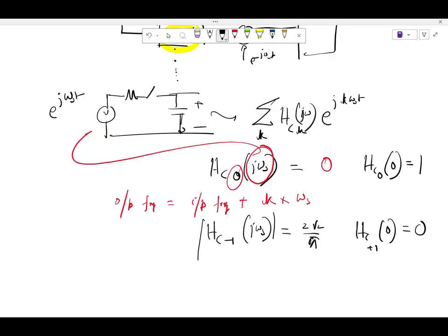One is finding out H(tau), putting that value. But today what we did, we took the assumption of a high RC time constant and related this with averaging, and we only found the transfer function from an averaging activity of the input sinusoid. So I did it only for the particular case of omega equal to omega s. Satisfy yourself by doing it when omega is away from omega s, maybe omega equal to multiples of omega s.